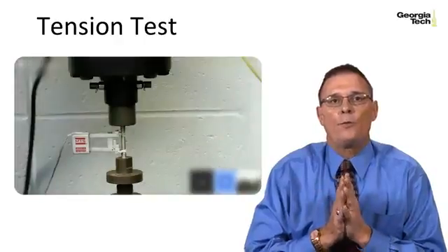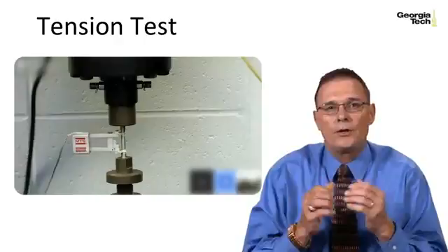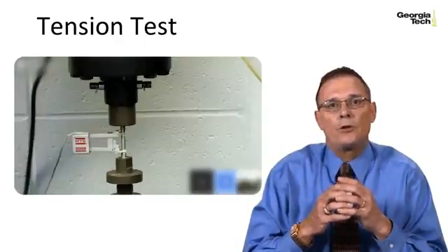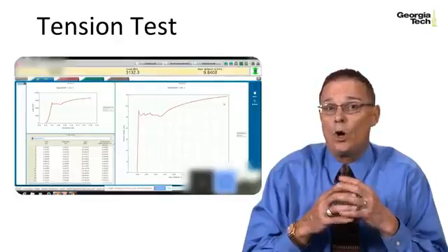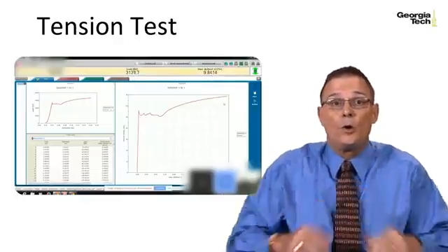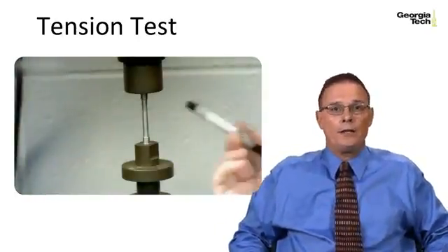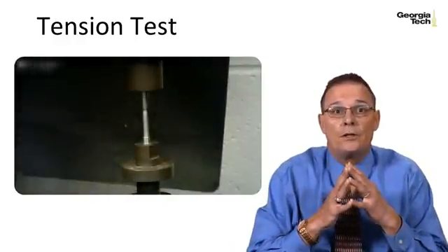The video starts off with a test specimen in a tension test apparatus. Notice that there is a gauge attached to the specimen to measure strain. As the load is increased, I've included the creation of what we will call the stress-strain diagram. As the specimen is continually loaded, you'll notice that it starts to neck down, or become smaller in diameter, until it finally fractures. The specimen used in this test is 1/4 inch diameter steel.